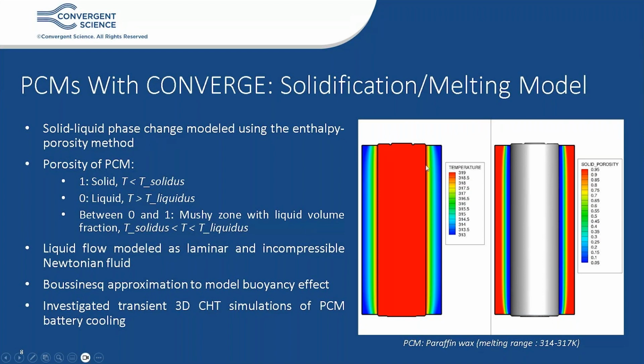As the battery heats up, the adjacent phase change material that surrounds the battery heats up along with it, and at a particular temperature range based on the material, it melts, absorbs heat, and regulates the temperature or fixes the temperature of that battery. This is becoming popular as it is a lightweight, compact, efficient, consistent, and sustainable method of battery cooling, and also versatile depending upon your selection of phase change materials.